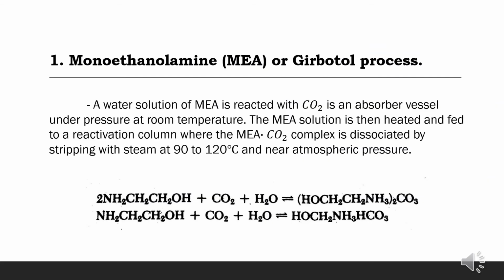So here in the slide is the monoethanolamine, or MEA, or Girbotol process, which I mentioned on the previous slide. In this process, a water solution of monoethanolamine is reacted with CO2 in an absorber vessel under pressure at room temperature.